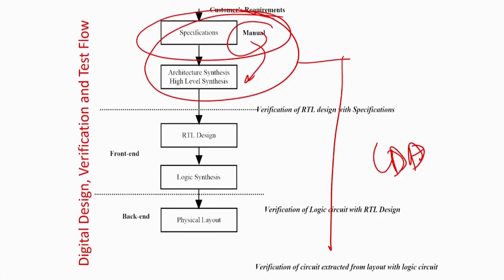So what is optimization here? This is an engineer's intuitive optimization, that given the requirement of speed, area and power, how we can design the circuit at the block level. There is no CAD involved here. We will also see basic design styles which can give you good quality inputs. If you give a very bad quality input to the CAD tool, you are going to get a very inefficient circuit. So here optimization is how, from my intelligence, I can solve the given problem in a more optimized manner,